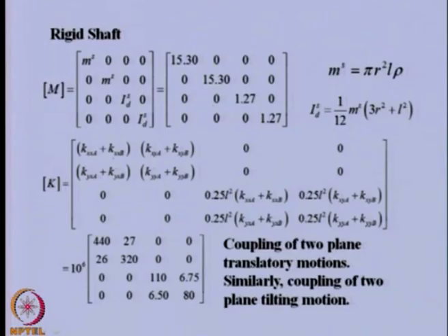The stiffness coefficients which are given can be written as this stiffness matrix. You can see these two stiffnesses of the two different bearings are getting added up here. So, there is a small change in the stiffness matrix which we obtained earlier. It was symmetric, so we had 2 kxx, now they are different, so we are adding them separately. Similarly, this. If we substitute the given values of the stiffness and the length, we can get the stiffness coefficient matrix like this.